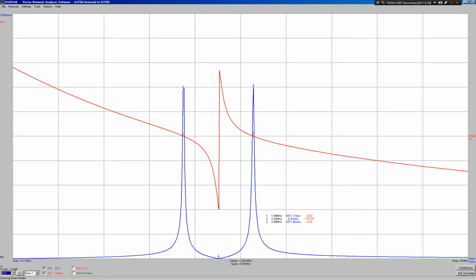Let's see if our balance is maintained. Do another sweep. Yes. Well, let's put it on continuous. That's a nicely balanced point. That is a good place to drive that cylindrical coil at. We've got a reasonable balance between the electric and magnetic fields of induction. The Q is good, and we have a range of different driving points here depending on our matching to the generator and where we want to actually drive.